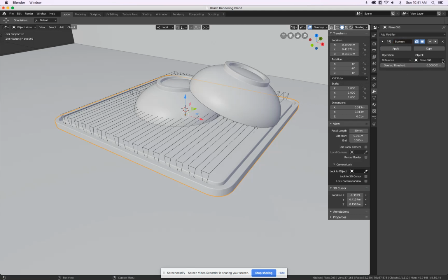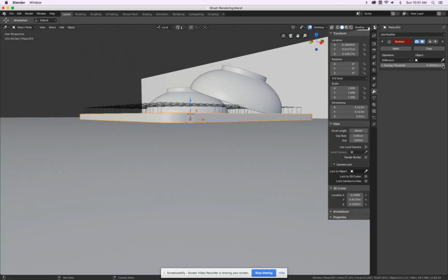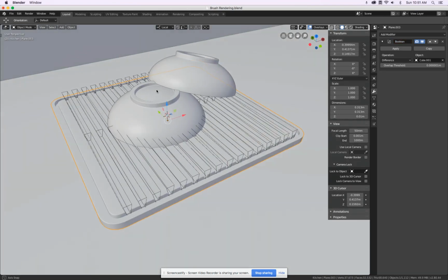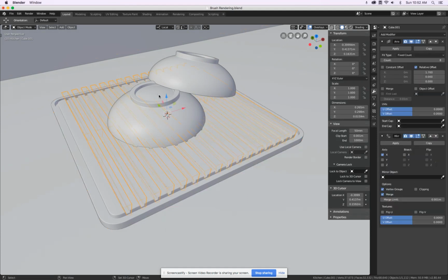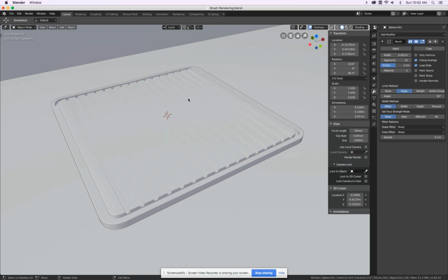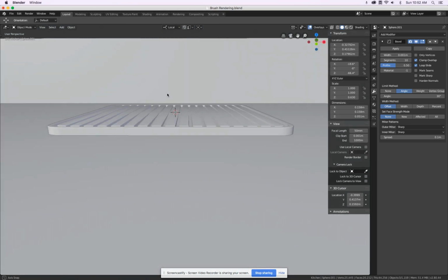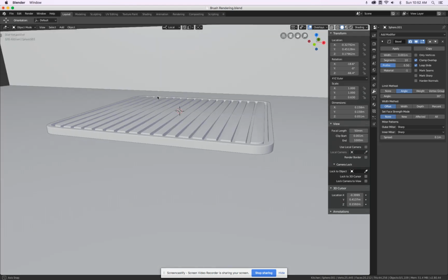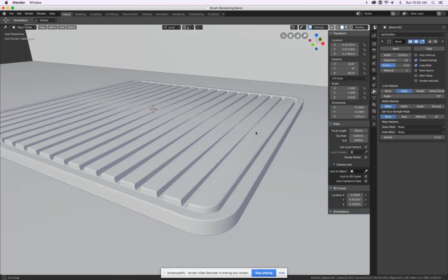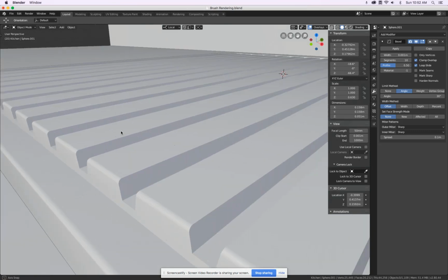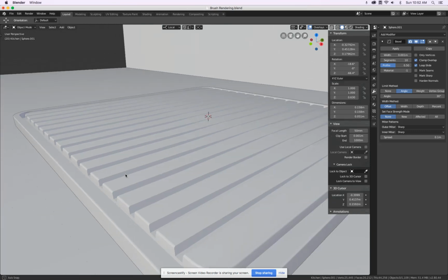and then I select my pad, go to modifier, Boolean difference, select, no, not the plane. Maybe from here, this is easier to select. Cube there. Cool. I can just select maybe these 2, 3 and hide them for a second. And there we can see what we did. This goes a little bit too high in my case. And here I can go down a little bit more.